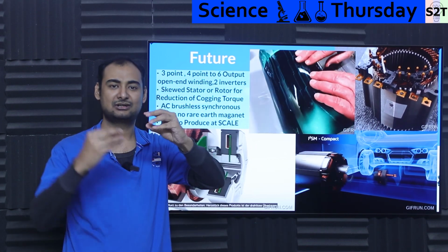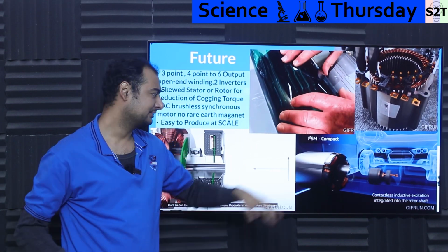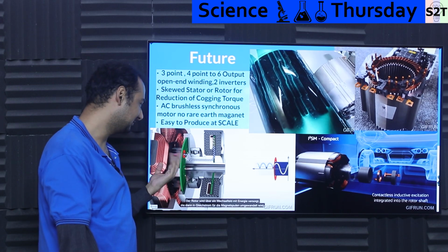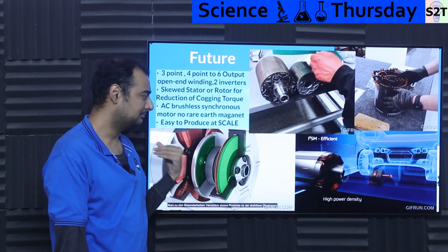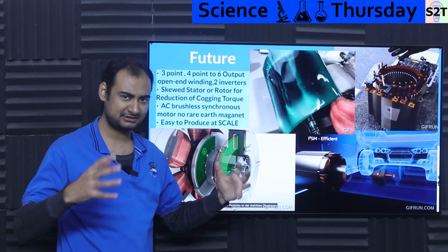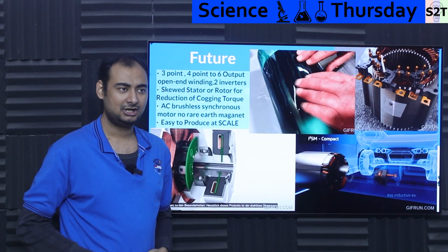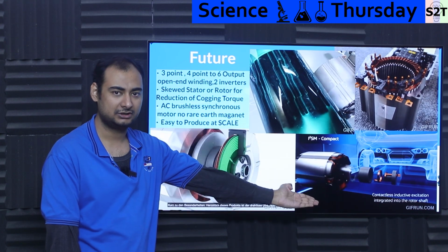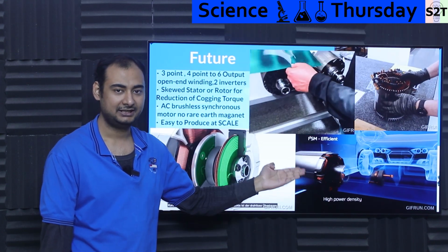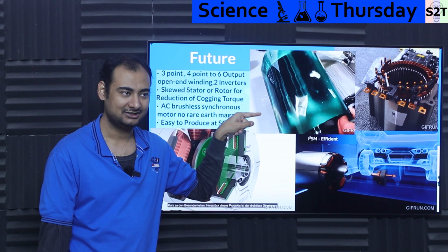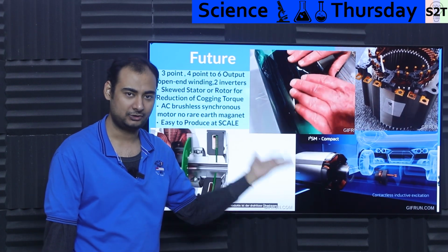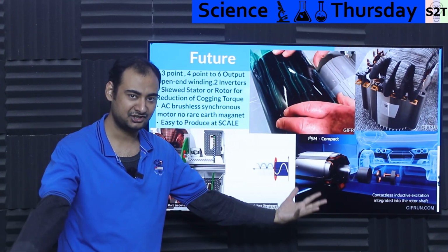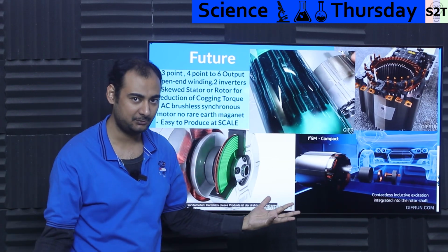And this company has figured out how to have that in the hollow shaft itself. So in terms of packaging, this is better. I think it should be better in terms of cost. Although both of them feel stupid to me. It's like, this is awesome. Motor awesome. Engineering ultra awesome. Why the heck do you have hairpin in the stator, not in the rotor? Rotor needs hairpin. Why? Hairpins are awesome at DC. What does have DC in here? Rotor. We have been making power plant generators for 1 century with hairpin.